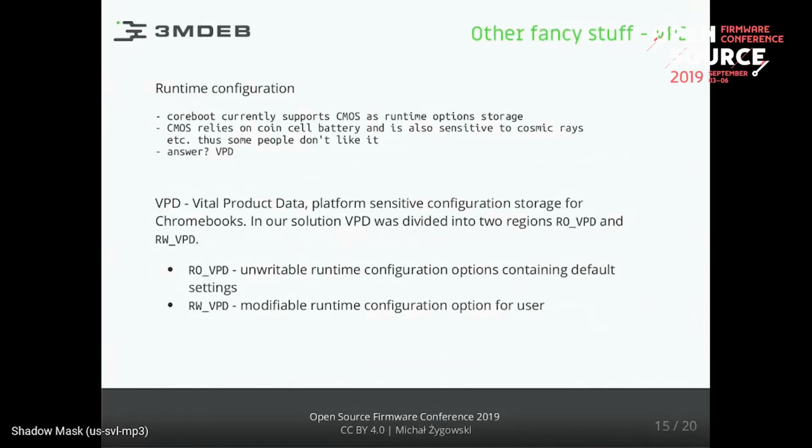What is more, the VPD also provides a utility for user space that can freely modify either the firmware online on the SPI flash or directly manipulate the file. So we can prepare our own binary and runtime configuration before flashing.